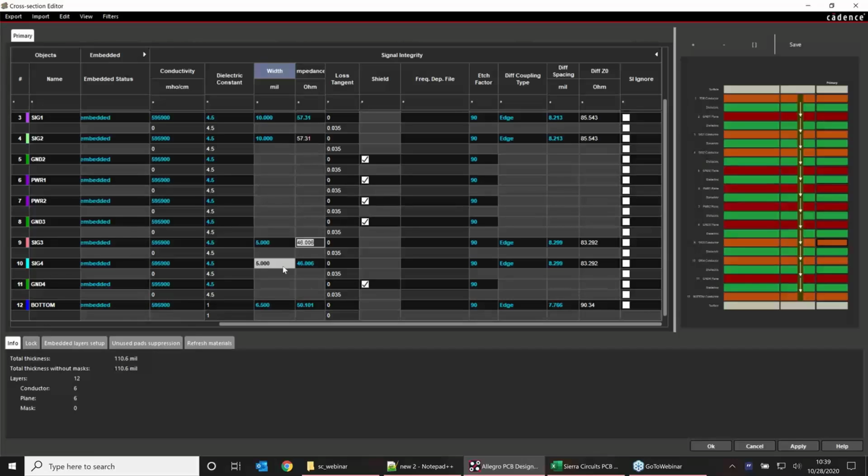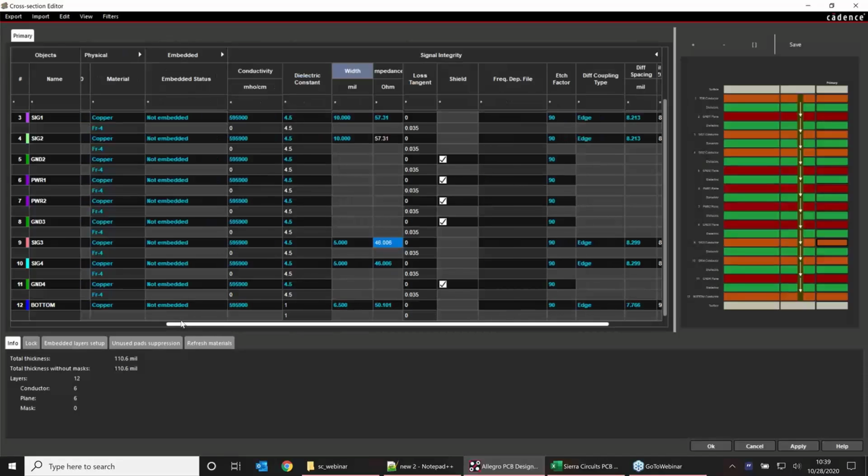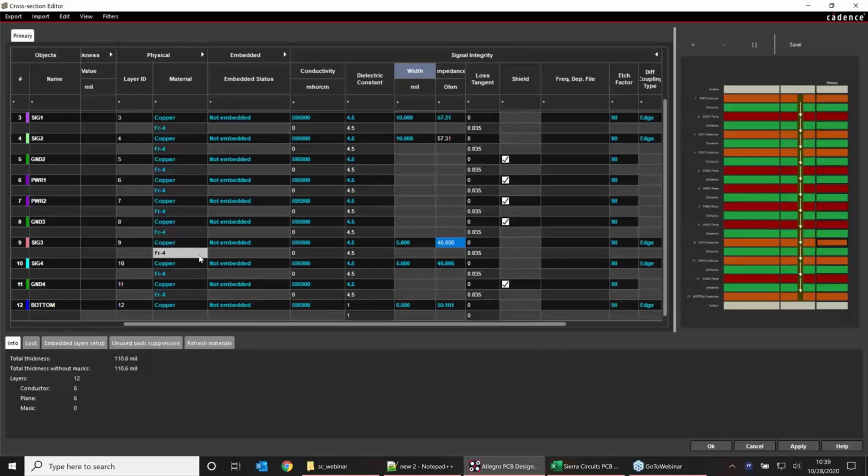So you can kind of play around with this. You can balance different things. There's going to be a lot of riding also on the materials that you pick. So in this case, I'm using FR4, but if you want to say, well, I need to try some different materials, I'm not able to achieve physically what I need with the materials that I've had, you can go to some higher quality materials, and you can see you're able to lower your impedance a lot just by choosing a different type of material for that. So if lower impedance is something that you want, maybe a different material type would be appropriate for you, but you can definitely play around with these and find the balance of what you want compared to what you need to get.